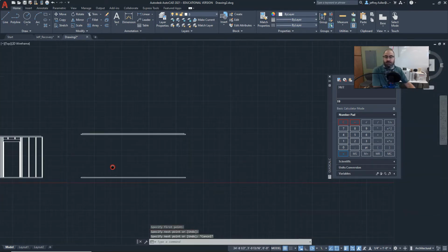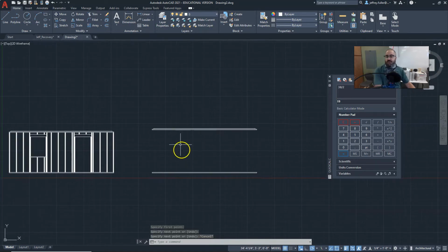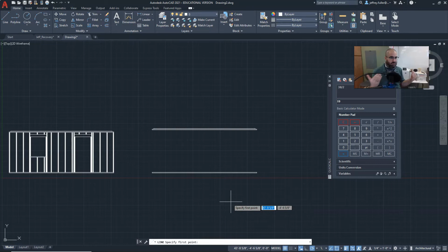Okay. All right, next thing we want to do is position our windows and doors. Depending on where the plans say we're supposed to put them, we start with the middle. If we have a set of plans, it's going to show us where the middle is. And remember, back when we were dimensioning these things, we dimensioned the windows and doors all to the center, not the ends. We dimensioned them to the center. So let's just draw a line here.